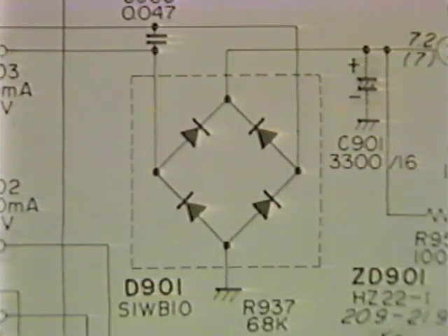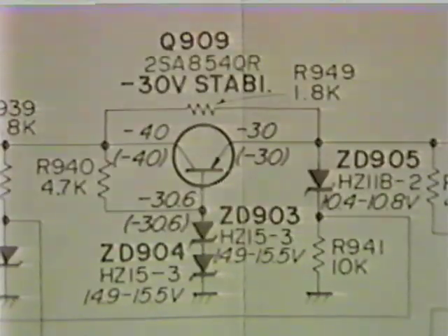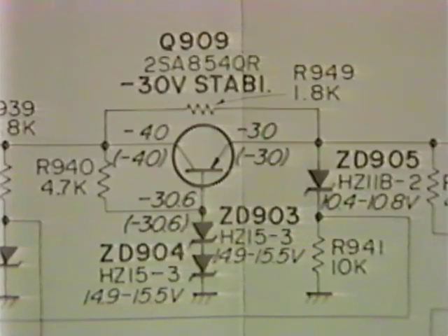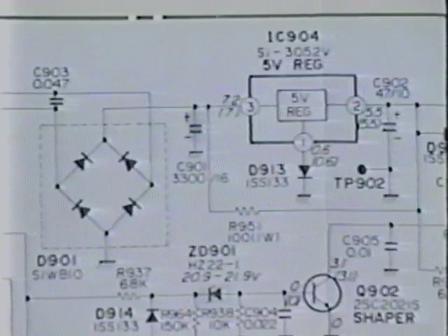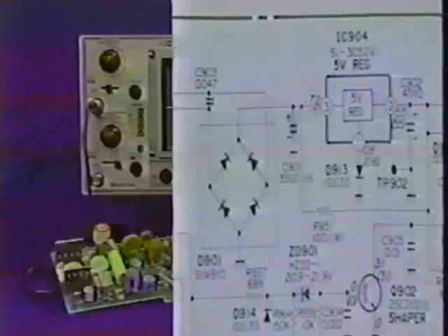A higher current circuit may include a multiple capacitor filter and a high current regulator implemented with a series pass transistor circuit. The digital circuits are often powered by 3-terminal regulator supplies. Each supply is carefully designed for economy and efficiency.